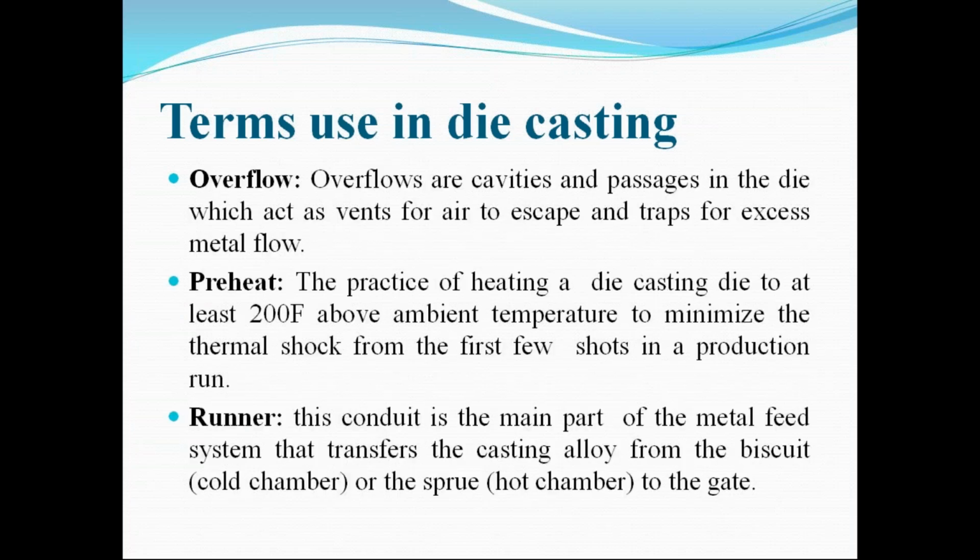Next one, this is overflow. Overflows are cavities and passages in the die which act as vents for air to escape and traps for excess metal flow. Intentionally we design the die that way. There is some excess volume of liquid material in some particular zone of the product.